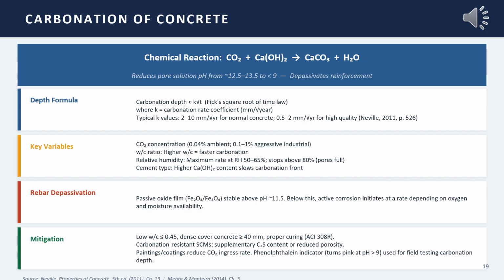So I will be briefly covering this slide, which is about the carbonation of concrete. Remember that carbonation is a chemical process that progressively reduces the pH of concrete over time, ultimately leading to the onset of corrosion. It's slower than chloride attack in most cases, but it's relevant to virtually every outdoor concrete structure.